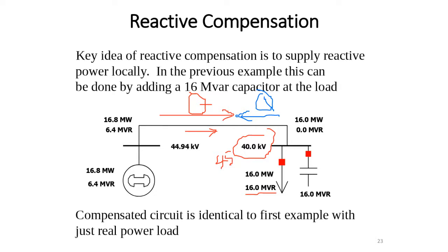What about reactive power? It depends on the voltage magnitude. The voltage magnitude is higher, therefore reactive power will flow from higher to lower magnitude. For the angle, the real power will flow from the bus or node that has a higher angle to the lower angle.